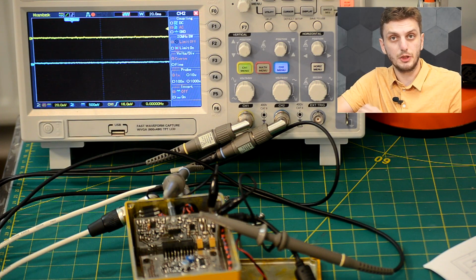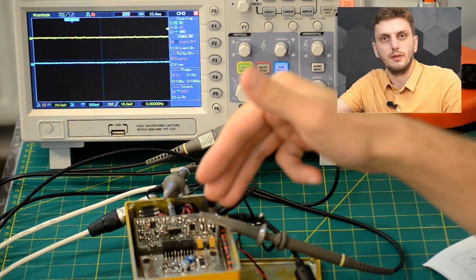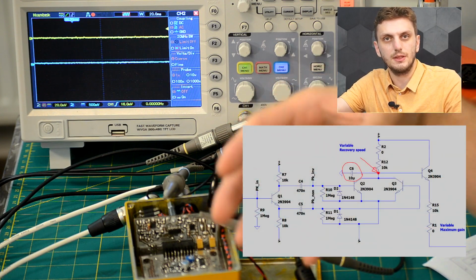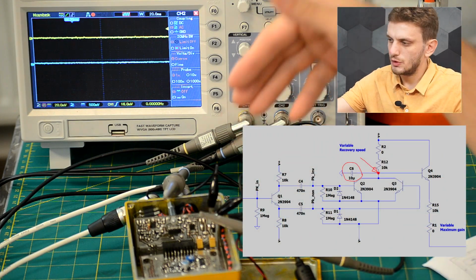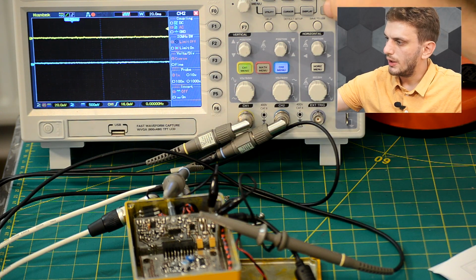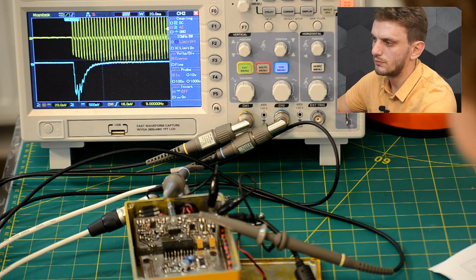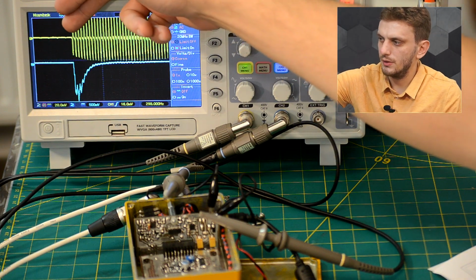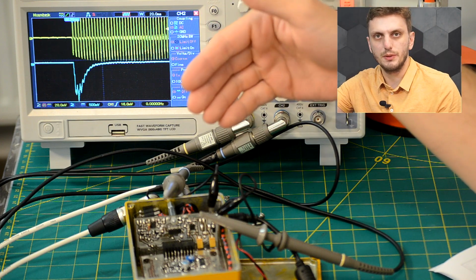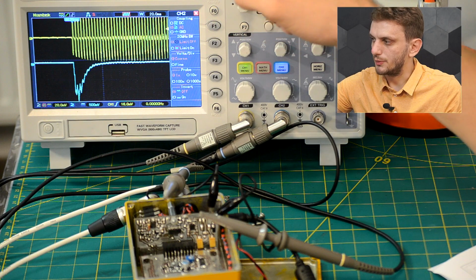Now, there's one more measurement I want to show you, and that is the voltage present on my electrolytic capacitor. So the buffer capacitor, that is setting the rate of gain change. So right now my second channel is directly connected to the capacitor, and now if I just strike one of the strings, you can see that as the signal is being applied, we see the voltage on the capacitor dropping. So my transistors are detecting the peak voltage and applying it to this capacitor.